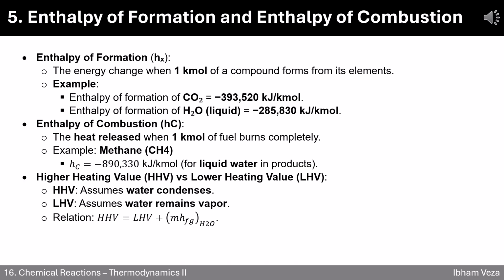Finally, we have higher heating value, HHV, and lower heating value, LHV. HHV assumes water vapor condenses back to liquid, capturing more energy. LHV assumes water stays as vapor, so less energy is counted. The difference between them is simply the energy from condensing the water formed during combustion. This distinction is essential when comparing fuel efficiencies across different systems.